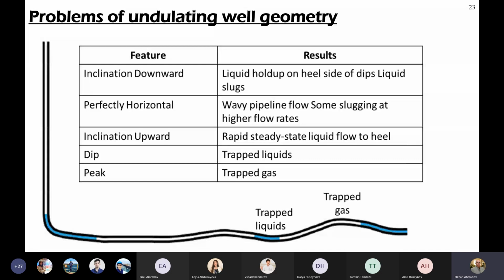the separated flow of gas and liquid, which is called slug flow, when a portion of gas goes through the tubing and then a portion of liquid, which creates instability in the tubing in the wellbore, which causes unstable wellhead pressure.